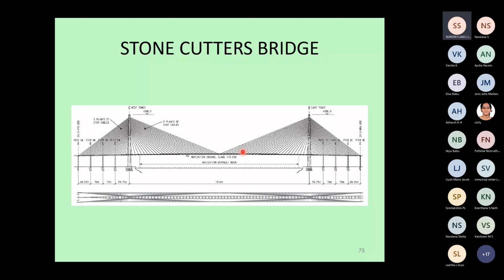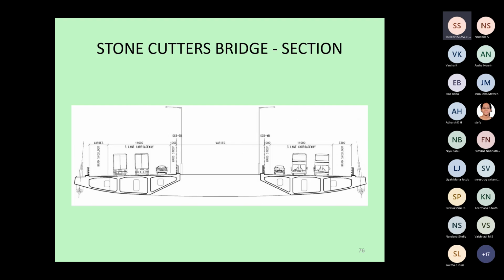You can see a close-up view of that on the bridge. There are a large number of cables placed at almost equal intervals, and each one is tied back to the tower and balanced by cables from the other side. So it's a balanced cable stayed bridge. There are also bridges which are not balanced and are tied from one side only. You can search for images of such bridges on the web and identify the different types.